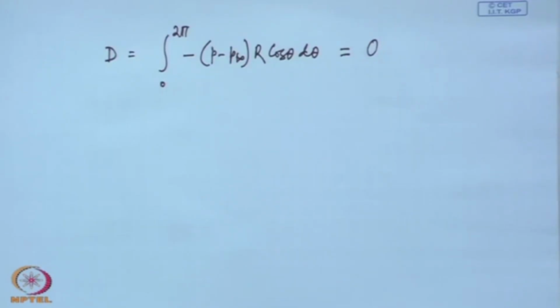And we see that as far as finding velocity, at least if not for the circular cylinder, because the circular cylinder case is a little different, even though we have solved the flow for a circular cylinder, but we will tell why the circular cylinder is a little different from others. But when we apply this to airfoil-like bodies, we really get very good results as far as lift force is concerned, even the pressure field and velocity field, but when you come to drag, it gives straight away 0. Even for a circular cylinder, which has a very high drag coefficient.